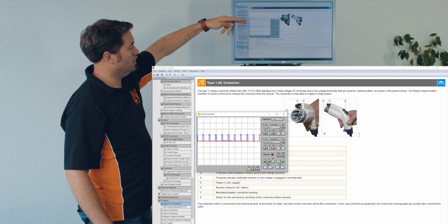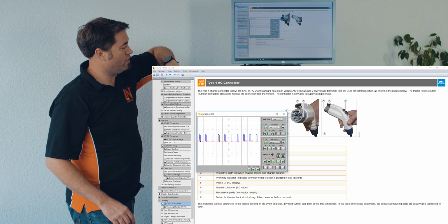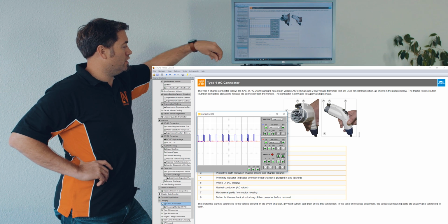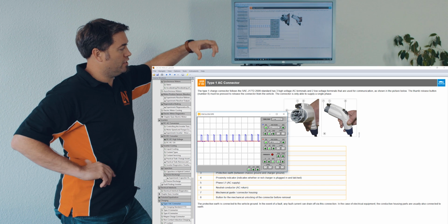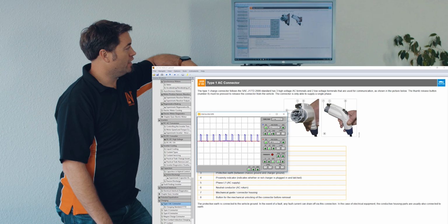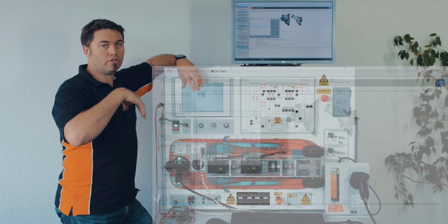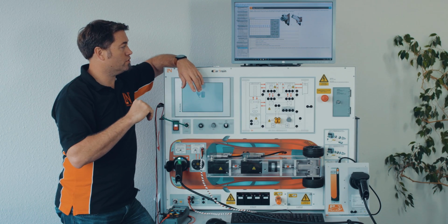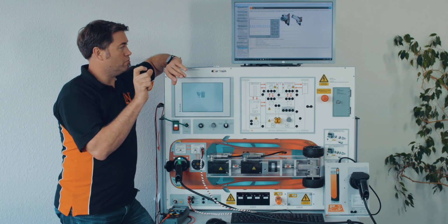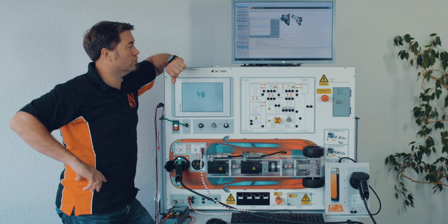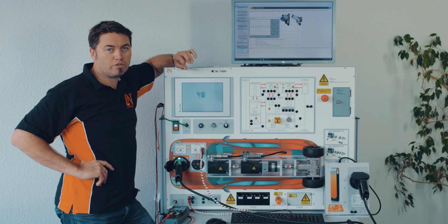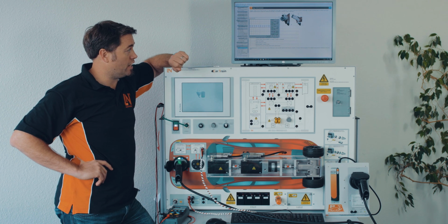So we're seeing this here. Now, there's various means of what this actual signal is telling us. On one side, there's the pulse width, the duty cycle, and also the voltage varies as well. So 12 volts, 9 volts, and 6 volts, depending on the condition, if the vehicle is ready to start. Also the amount of duty cycle is the vehicle telling the supply equipment what is the maximum charge the vehicle can take at that point.